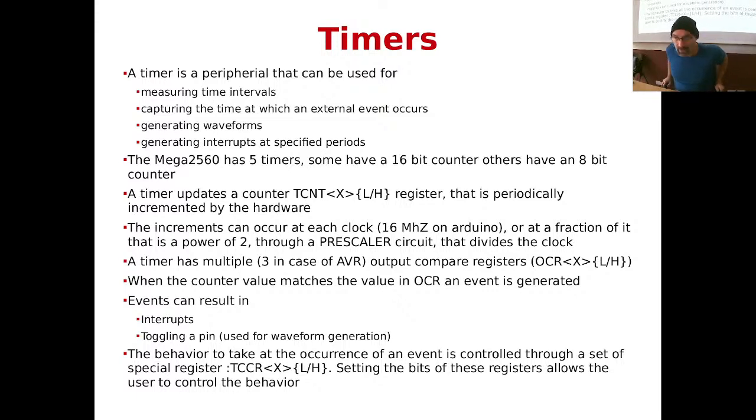Very intuitive. You could also use a timer in this way, for instance, if you want to read a sonar. A sonar device is a sensor that measures the distance through the echo of the ultrasound. You fire the sonar, the sonar sends a ping, and then it starts listening, and when it hears the ping, which is itself shooting back, it stops counting, right? And this way you measure the distance with the timer. Okay, an example of how to use the timer in counter mode.